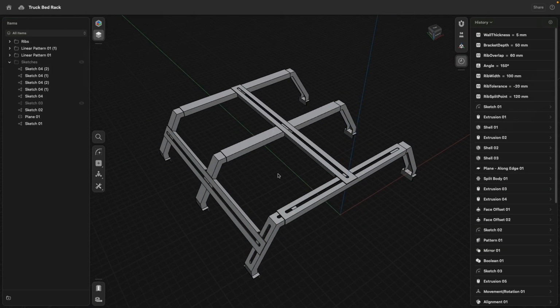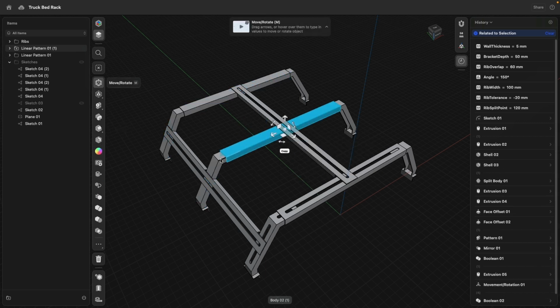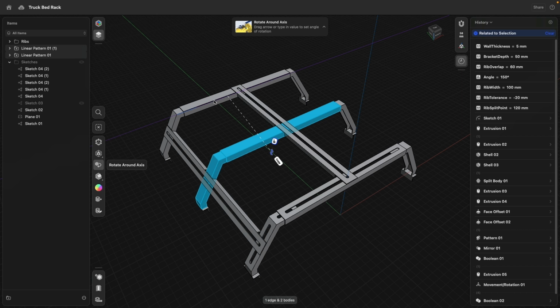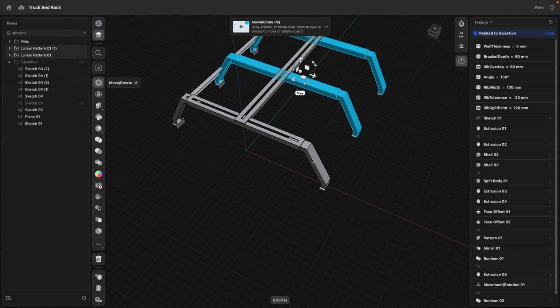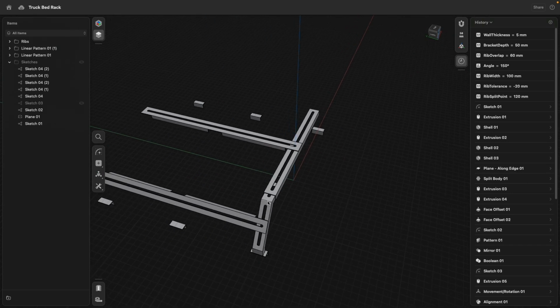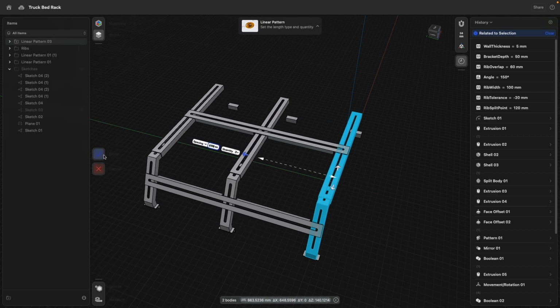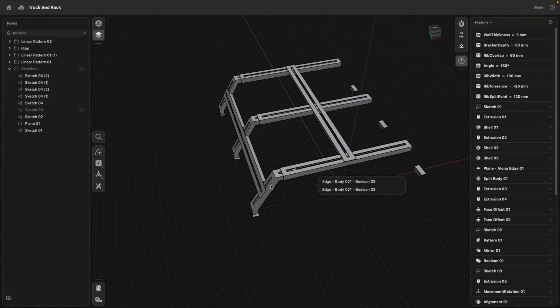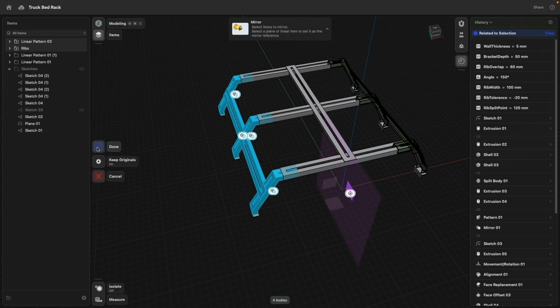Very good. Okay. Very last method cleanup. You see we do have these others. What do we do with them? This is a case where since we are exploring this design step by step without having an initial, how could I say that, construction plan to execute, I will delete all the parts I now don't need anymore. So I select them. There we are. Beautiful. And then I recreate them with a pattern command again. And this one, this one, this one, and this one I will mirror over to there. Perfect.